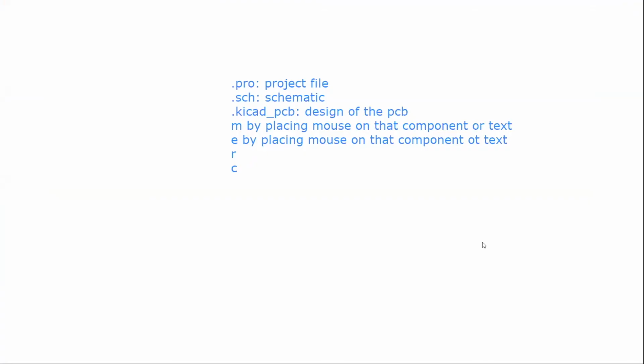Rakshita, does it matter which footprint we select for a particular component? Yes, it does matter. We need to know which component to place there. How can you place components if you are ready with your PCB? Now you have to place the component. If you don't know which footprint you had taken corresponding to your symbol, then you are not able to put the symbol on the footprints which you had assigned with your symbols in the schematic.